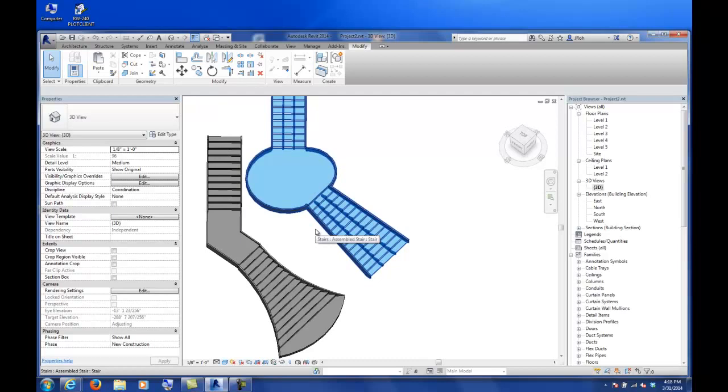Last component I want to go over, and then I can open it up for questions, is using the railing tool to customize a railing that's not just straight up and down. If you want to angle it, or if you want to make a sunshade system or something else, such as in other classes we've used the railing tool to make railroad tracks. If you look online, you can see people making anything you can imagine that repeats over and over again, because that's basically what the railing tool is doing, right? You've got the baluster that's being repeated by a certain distance in a pattern, and then it's got a set of extrusions that are happening based on your profile.